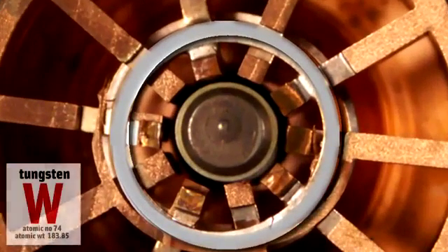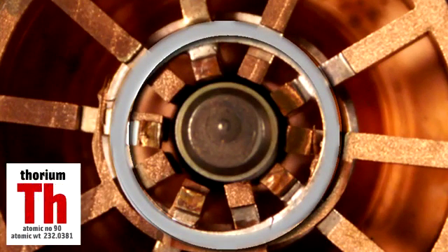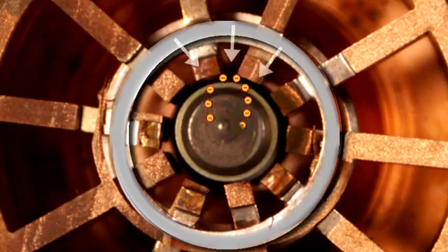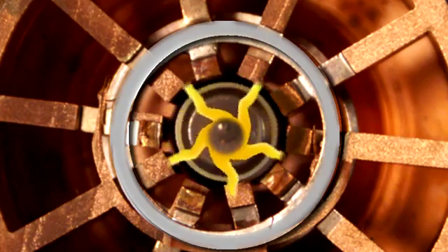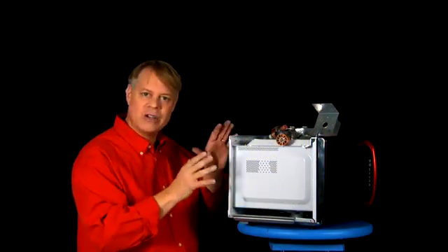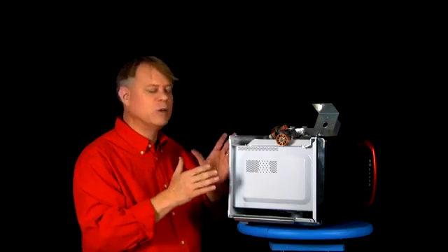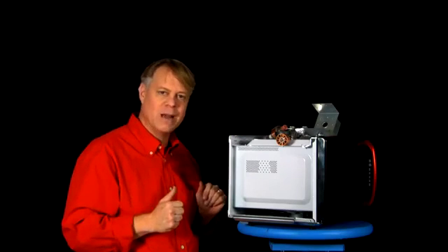The filament is made from tungsten and thorium. Tungsten because it can withstand high temperatures, and thorium because it's a good source of electrons. The magnets bend these electrons so that they swing back toward the center filament. We adjust the magnetic strength so that the now orbiting electrons just brush past the opening of these cavities. Like blowing over a half-filled pop bottle to make it whistle, this creates an oscillating wave, the microwave radiation that heats food. It's simply astonishing that these cavities can be made with high precision, low cost, and incredibly high reliability.